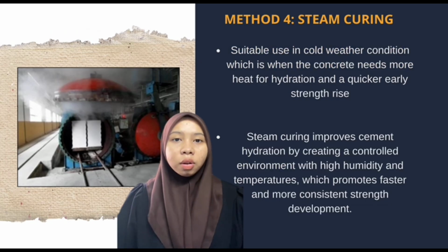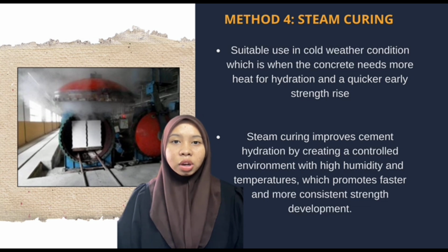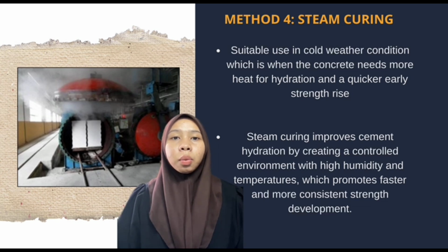The other method of curing concrete is the steam method. Concrete sections are cured by the use of steam or water vapor. This method is suitable for use in cool weather conditions, when the concrete needs more heat for hydration and a quicker strength gain. The steam method is one of the prevalent techniques for precast RCC pieces.